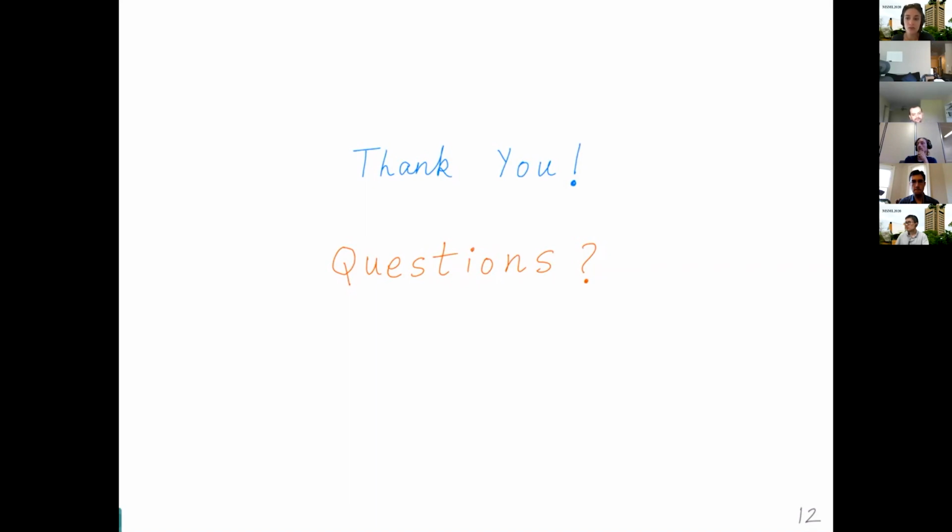And the other thing is, it's really easy to get a spline to converge with a circuit simulator. With deep neural networks, the problem is they don't work so well in circuit simulators unless you're very careful about constructing the model. The circuit simulator very often fails to converge. But if you get it right, they can be very fast and very memory efficient. So you have these trade-offs here.